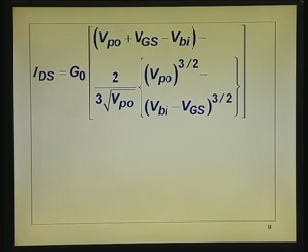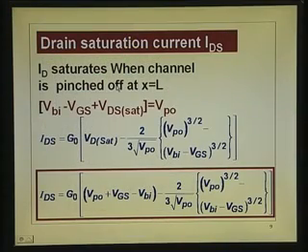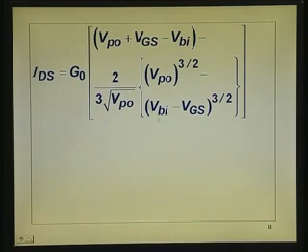We have written there Vds is equal to this quantity, saturation voltage. In fact, if you see the previous equation that we have written, let me go back and show you. All that we do is meddle with this Vp0 plus Vgs minus Vbi. The same thing I have written, that is Vd sat minus 2/3 of this quantity. So, what we have done is just rewritten those terms.